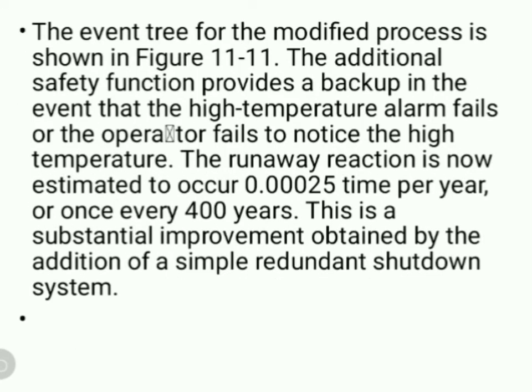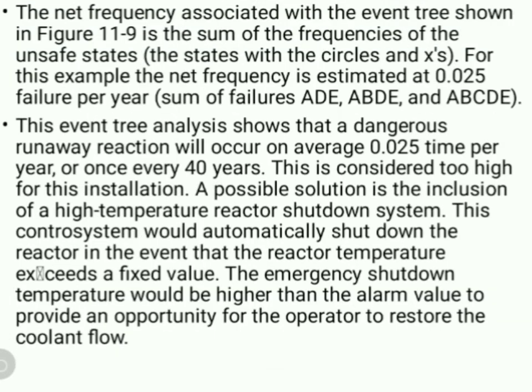Again we can see the runaway reaction. So this is considered too high for this type of installation. The possible solution is to include a high temperature reactor shutdown system. So after calculating the value, we have to give some preventive measures. Here the preventive measure is to install the high temperature reactor shutdown.